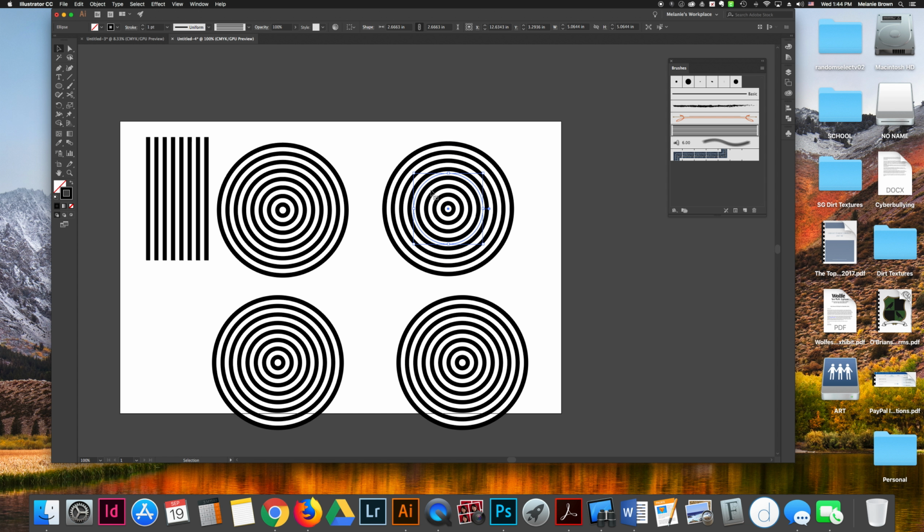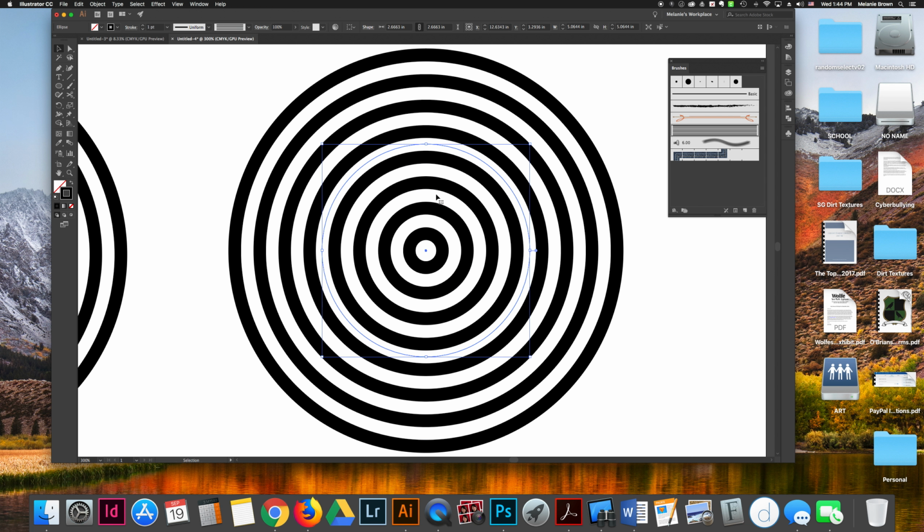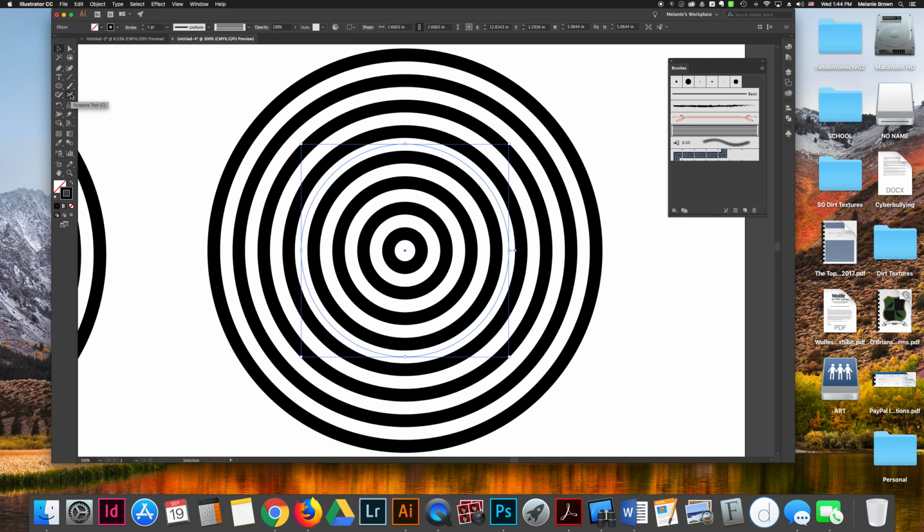Click on the second one. We are on the black arrow, the V. I'm going to zoom into that. We're going to now go to the scissors tool. It may not be on top. You probably will see the eraser tool and you will have to click on it and go down to the second tool, which is scissors. Once scissors is on top, to get back to scissors, all you have to do is hit the letter C. So V to go back to the move tool and C to go back to scissors. So you can toggle back and forth pretty easily.